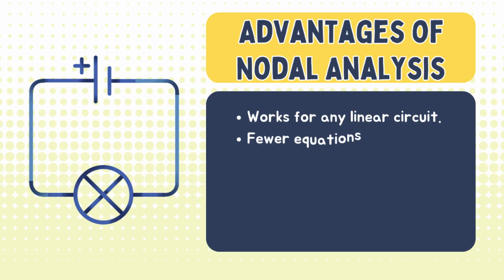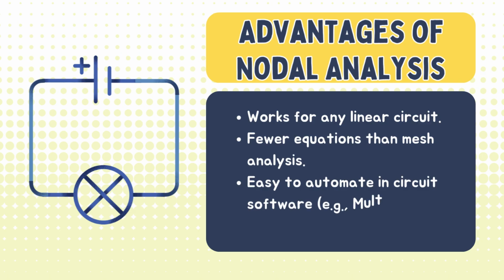Advantages of nodal analysis. Nodal analysis works for any linear circuit and usually requires fewer equations than mesh analysis. It's an efficient method that can be automated easily in circuit simulation software such as Multisim and LTspice.